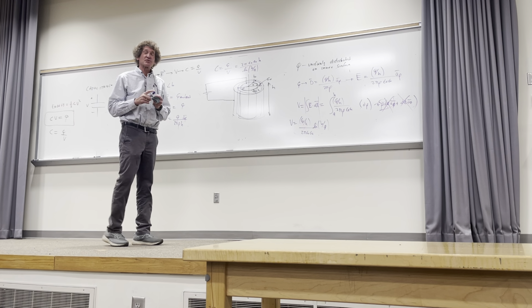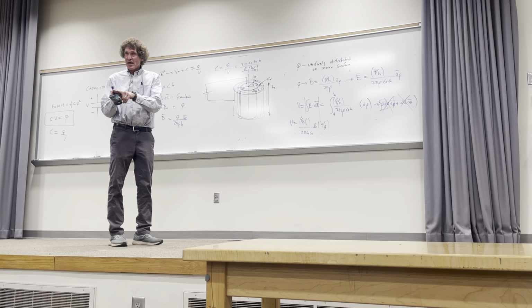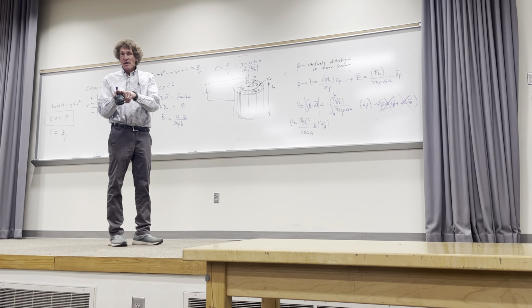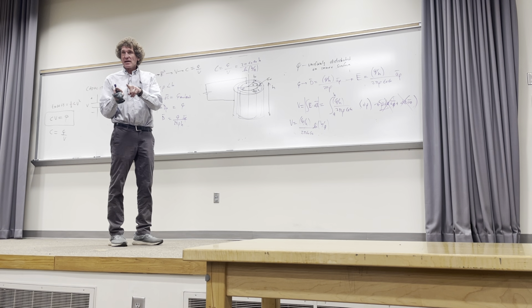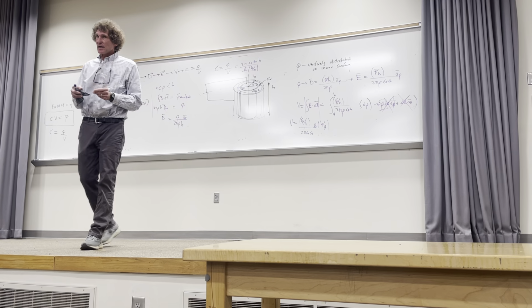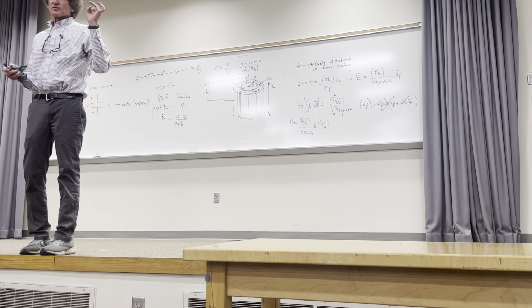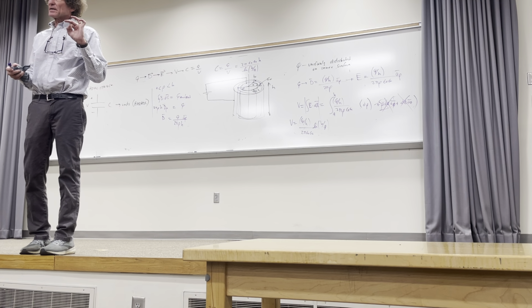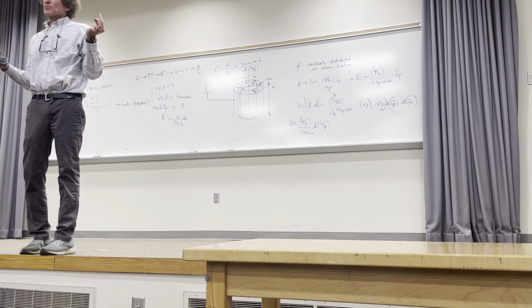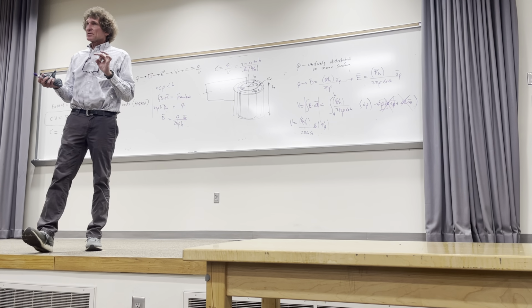So the breakdown strength is the reason they don't make them that short. And there's this happy medium. Well, what can you get away with? That's where the materials come in, like mica for the dielectric. Do you know what mica is? Mica is used for most of these small capacitors, like ceramic ones. It's a pretty good insulator. I actually don't know the breakdown strength, but it's probably about 8 to 10 times air, so 30 million volts per meter type of thing. That's pretty good. It's lightweight.